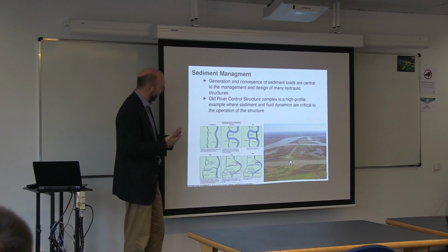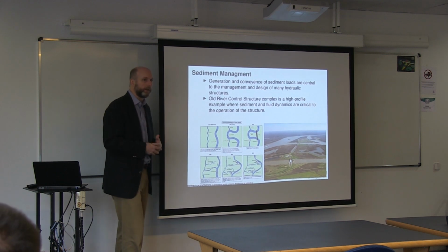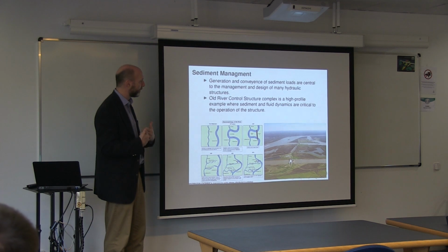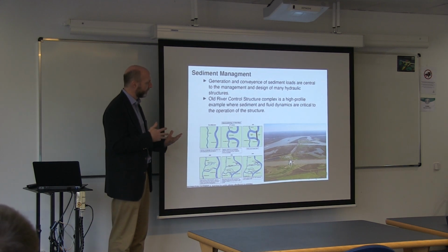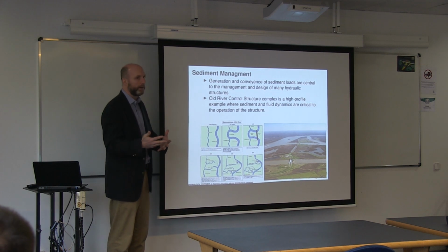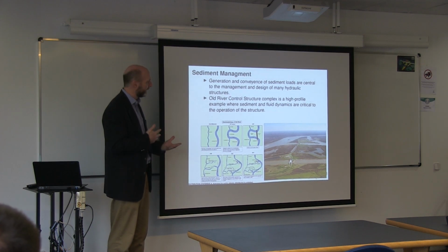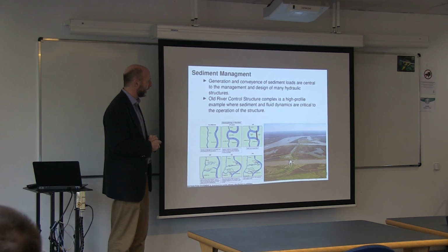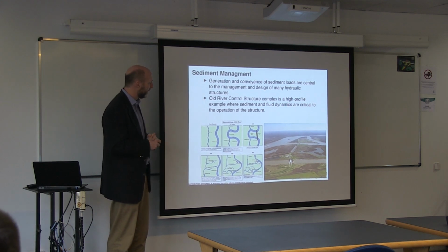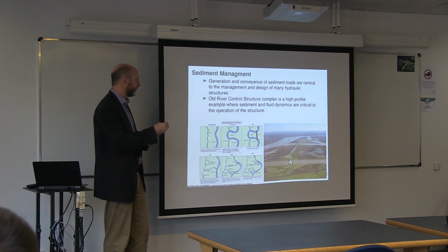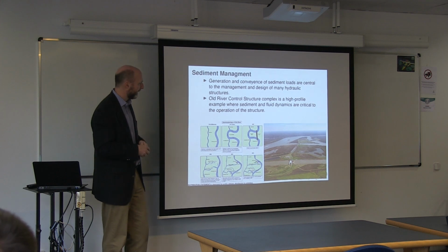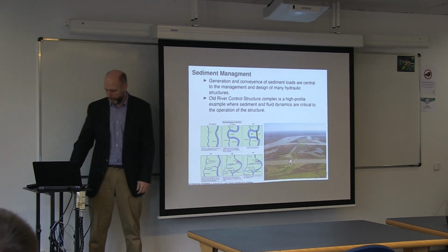But around this facility, sediment issues are very important. So the Mississippi River, of course, carries a lot of sediment. There are reasons why you might want to divert some of that sediment down the Atchafalaya, but at the same time, you want to protect against rerouting the entire Mississippi down the Atchafalaya. So again, interesting near field or near structure hydraulics interactions with sediments that are important here that we'd like to understand.